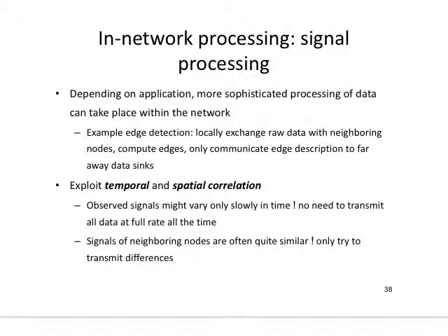So you deploy many sensors, and in this location you get readings from 10 sensors, aggregate, get the average. From here, aggregate, get the average, and so on. Okay? So this is spatial correlation. You know that these sensors exist in the same location, so you collect the measurements from them, you aggregate, and you send. Right? So this is the spatial correlation.